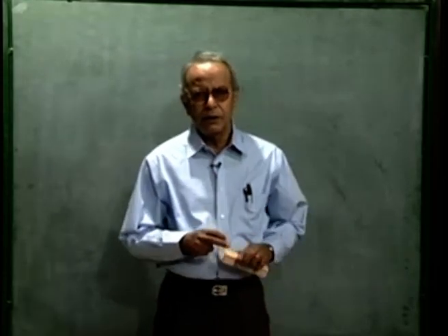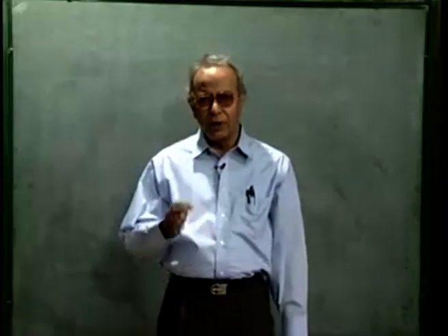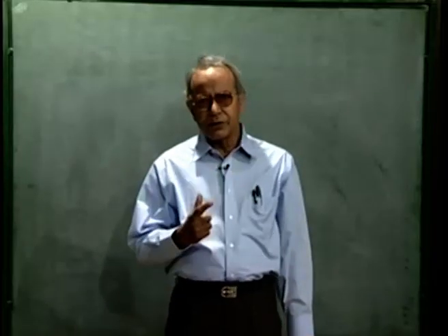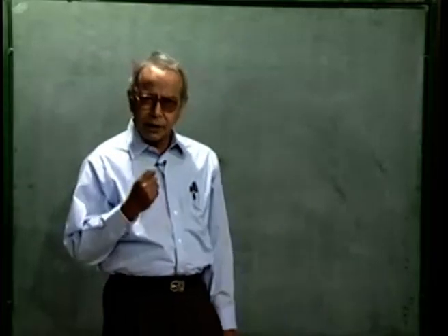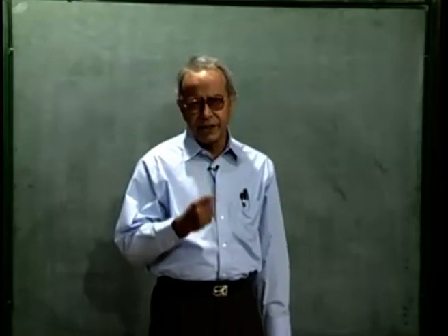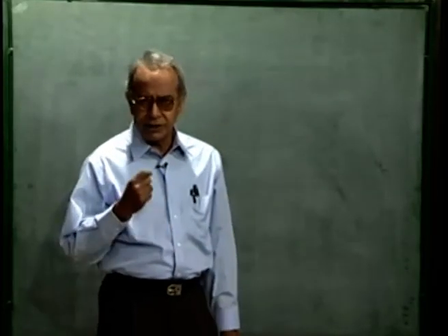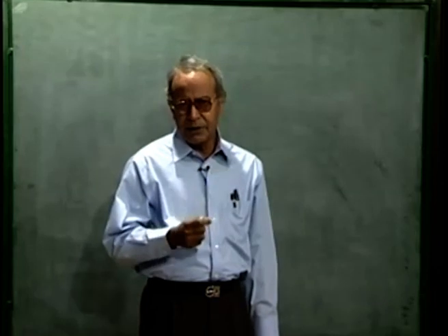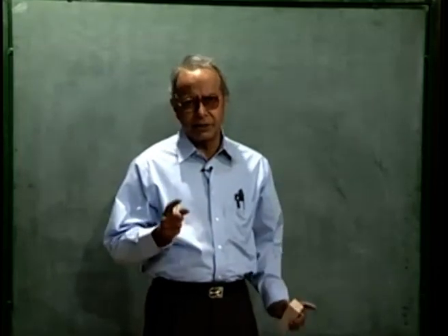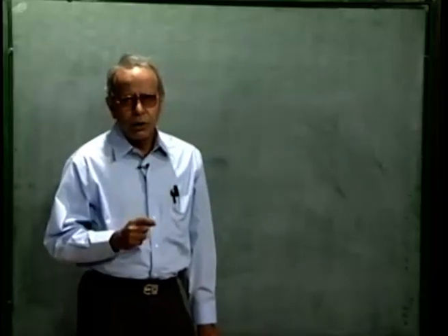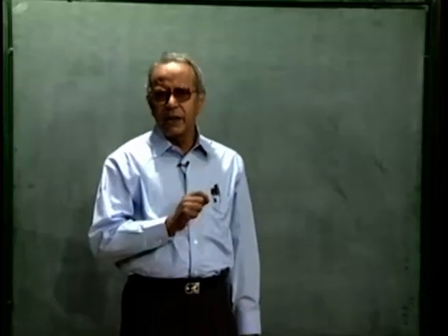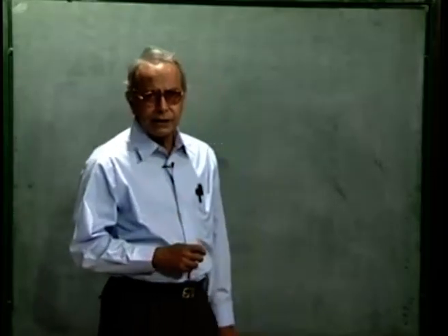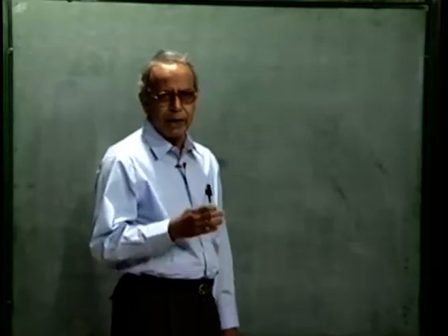In our last lecture, we have seen a number of four-link mechanisms, rather 4R mechanisms, the link dimensions of which were so fixed that a particular coupler point in each of these linkages could generate an approximate straight line, which we call approximate straight line mechanisms. That means the coupler curve had an approximate straight line portion, but it is known that by using four links we can never generate an exact straight line. In today's lecture, we will discuss what we call exact straight line mechanisms.